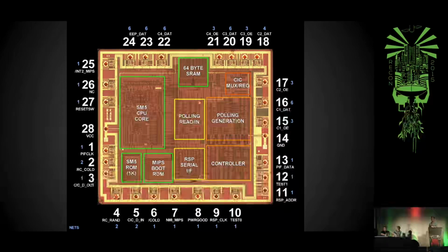So I'm thinking that these pins have alternate functionality, just like the CIC, and that we could use them for arbitrary code execution. Now, this is future work. We just discovered this like a week ago. But we're really hoping we could run our own code on this chip. This has its own 1K ROM as well, but it's actually fully utilized, unlike the CIC that is basically half empty.